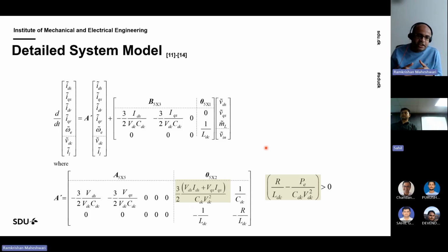Yes. And in the other case, you are changing the speed. So any disturbance or any sharp change will cause some issue on the grid side, or on the small DC link capacitor on the DC side or the AC side. It will directly reflect there, right? And this does not have any kind of energy storage to support those disturbances.